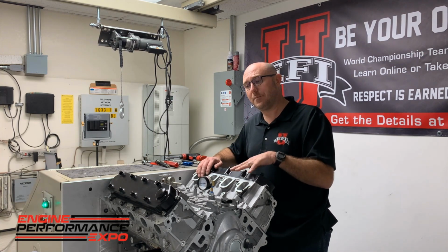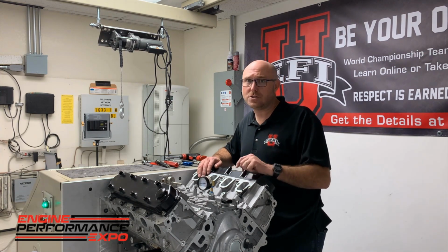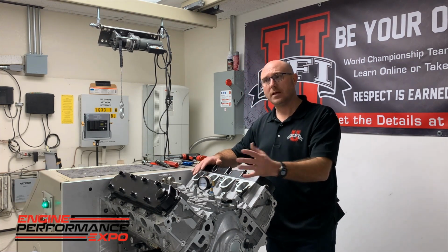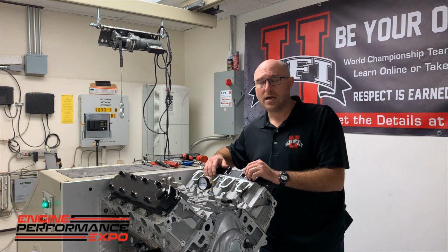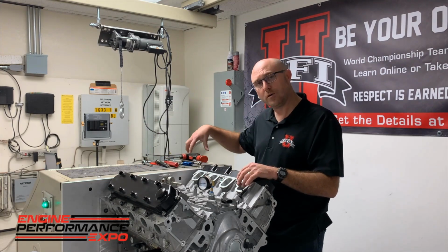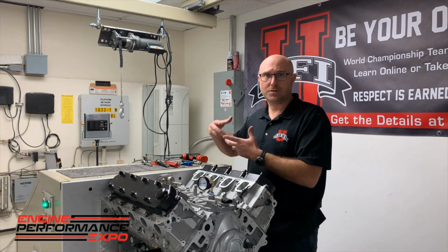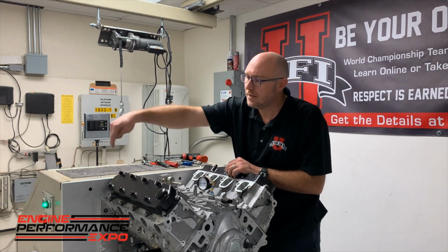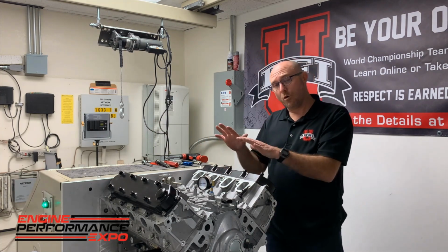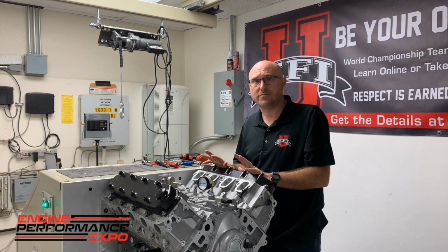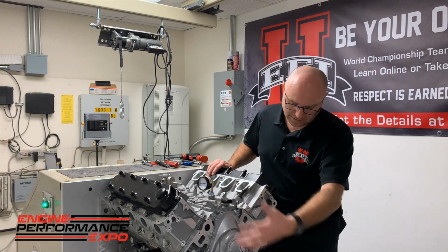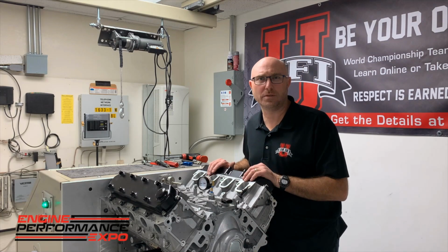So in order for that to happen, we still have to have all the lubrication for the engine. So we can either run a dry sump system that is included in your engine package. I also have a dry sump system that I run off the machine. So I have an electric motor to a set of pulleys that runs an actual dry sump oil pump. And then I've got a sump can over there and some feed lines and everything. Or we can run it like this engine, which is just a factory wet sump using the factory oil pump and supply and everything internal to the engine. So a lot of flexibility there.